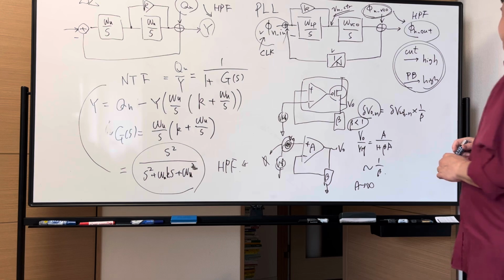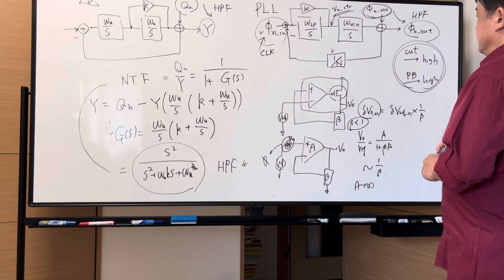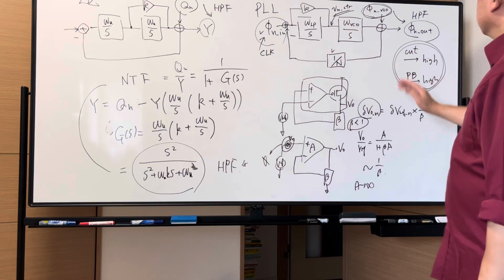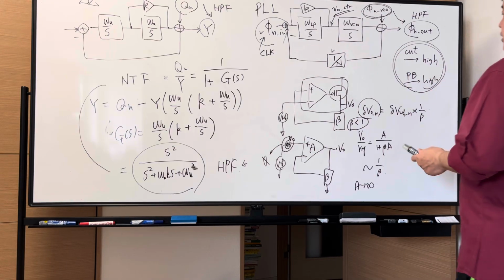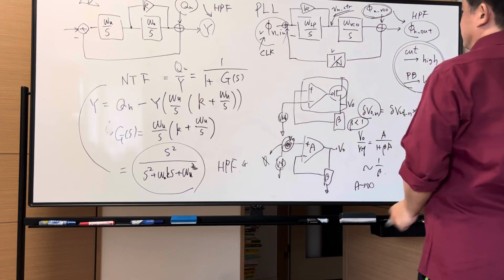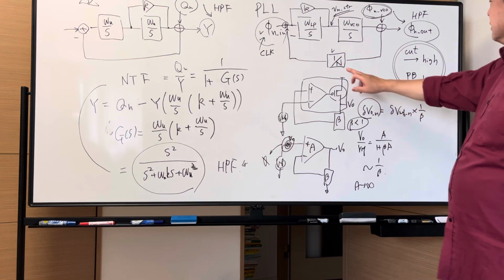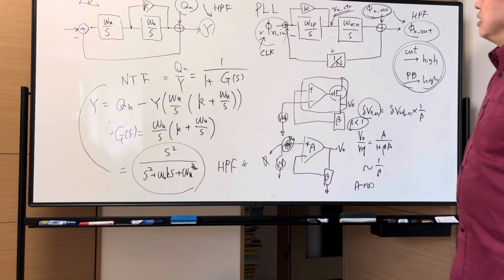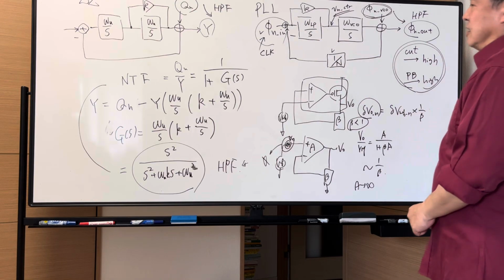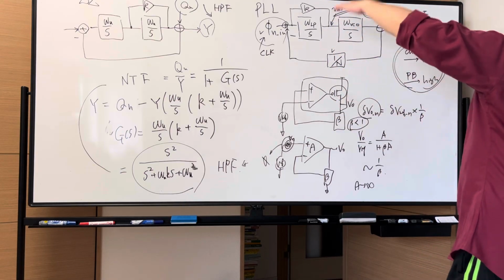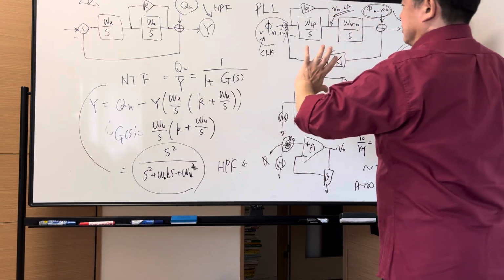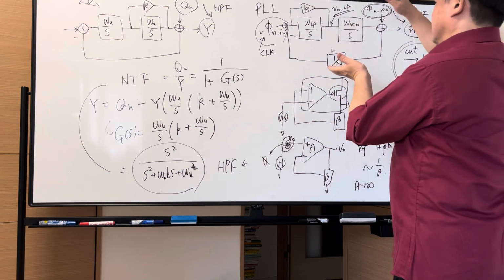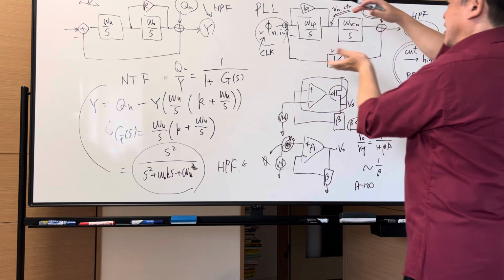So we need to optimize the loop frequency. But as far as these parts are negligible, for example, the divider and phase detector are made by logic circuits, and they have power rail noise. So, to decrease the power rail noise, we can apply a big decoupling capacitor.